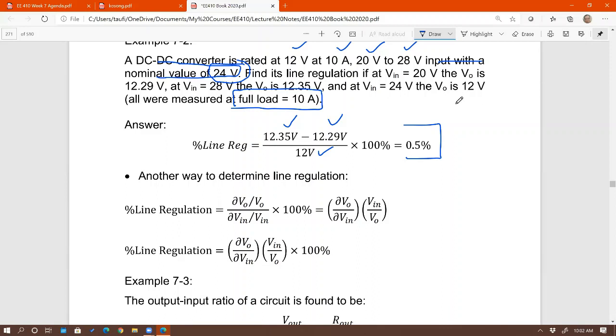Just like the output power that I answered in the previous question. Somebody asked previously. So things that you need to know before you design a converter are as follows: V out, percent V out peak to peak ripple. So you have to know these 2. And then P out max, you have to know this as well. And you can see from P out max and V out, you get I out. So I don't need to give you I out max. This is going to be coming from P out max and V out. Keep that in mind.